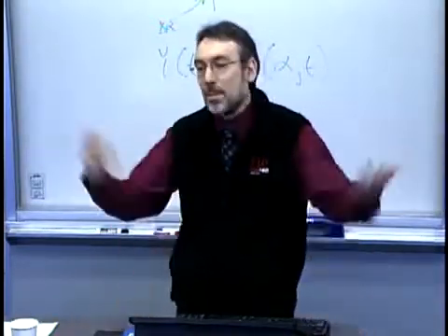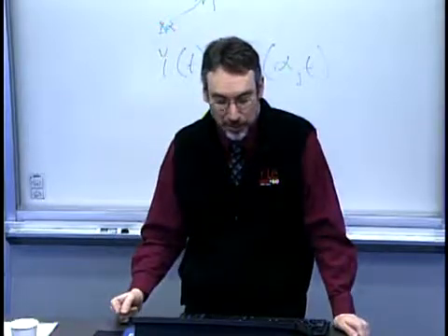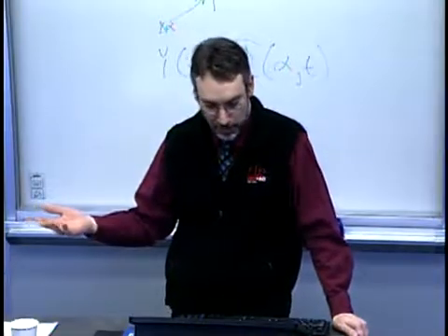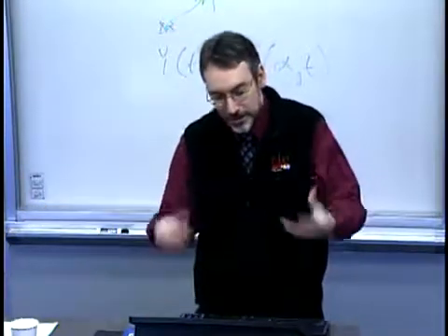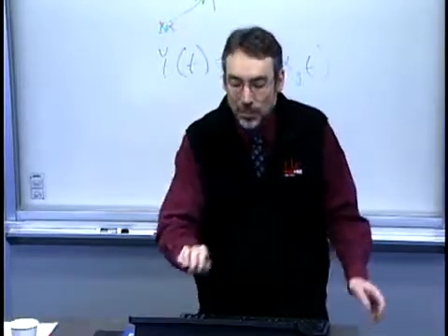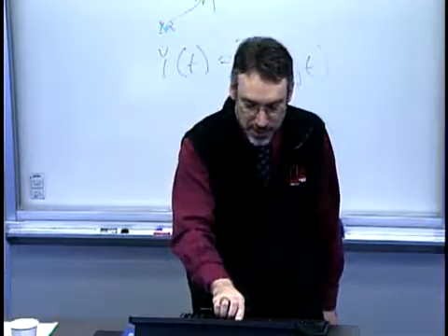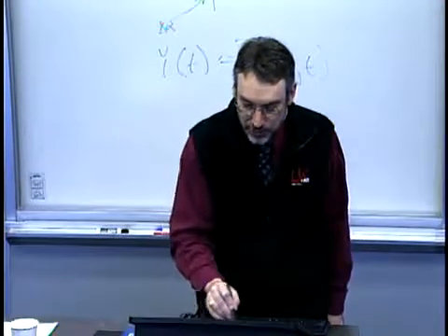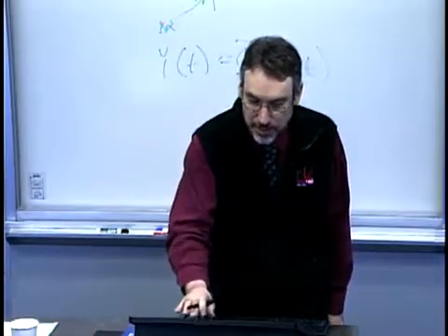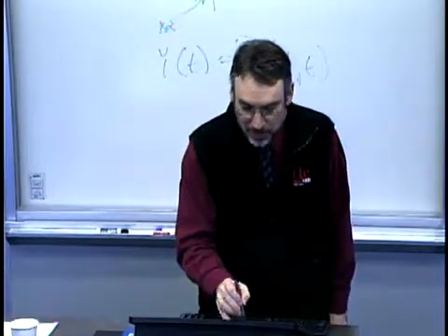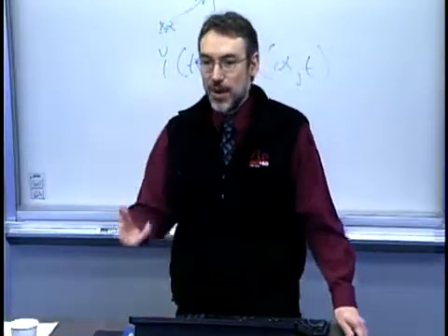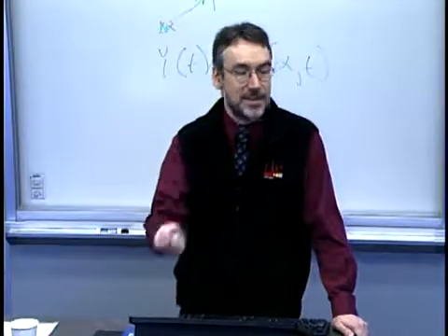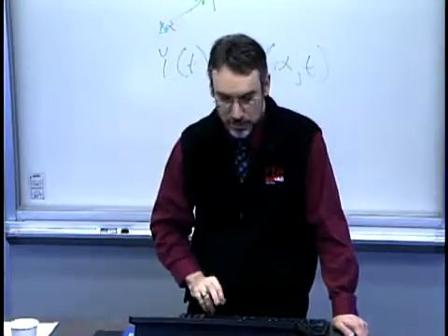Very interesting. So a couple of the points here, the kinds of things that we might be looking for here are deterministic and systematic kinds of effects that we might want to use modeling for. And then we also are starting to get close to the statistical process control thinking, which is to say we would like to be able to know what the inherent or natural variation of the process is having to do with these sorts of bands, and then be able to detect with high degrees of confidence that something strange has happened and I better take action. And that's SPC, or statistical process control.